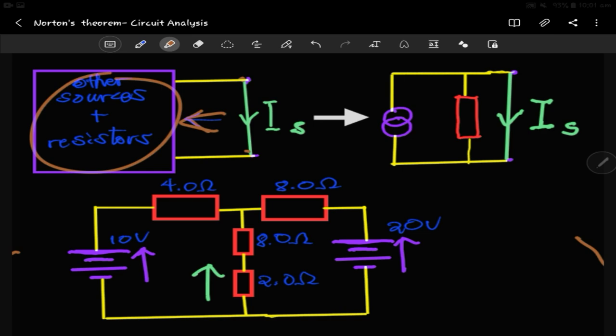But if you go through the procedure and follow through, you'll be able to simplify the whole circuit and get a current here. This symbol is actually a current source, or current generator. So simplifying it will give you this. You have a current generator here and the resistors, all simplified to this. But this current, because you are looking through this terminal, still appears here.